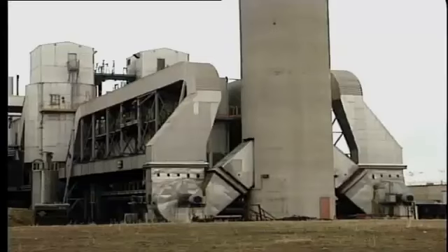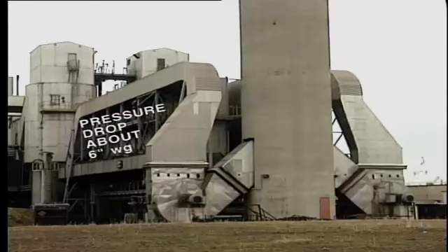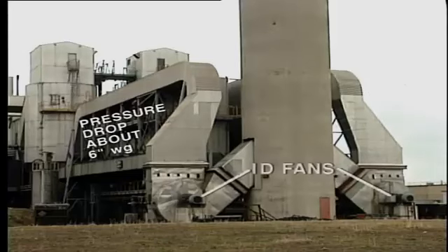The pressure drop across the fabric filter, or baghouse filter as it is known, is quite high, about 6 inches water gauge, as compared to 0.5 inches for the precipitator. This means that larger ID fans are required. One important point to know is that the fabric filter is not suitable for use with oil-fired burners. This is because the sticky nature of the particulates, in this case, makes cleaning of the filter bags extremely difficult.